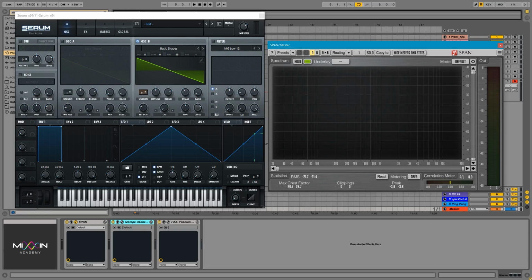How we actually determine the positioning of a subwoofer is by how the phase of the subwoofer's signal is going to correlate with the phase of our normal loudspeakers. So this is what determines the positioning of the subwoofer and not the actual directionality. In shorter terms, we can't determine where low frequencies are coming from. A good thing is that usually sounds are not comprised only of low frequencies, but they do have some higher frequency content involved so that we can decide where the sound is coming from. But if it's only low, you can't